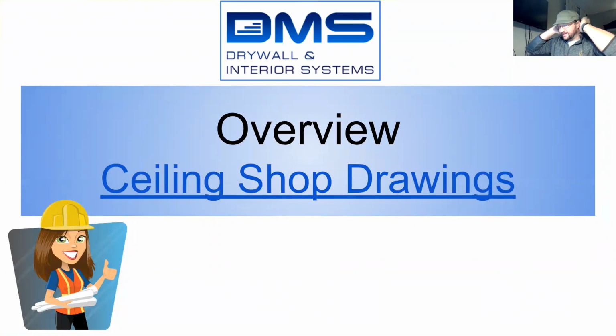Okay, welcome everybody. Today we're going to be doing an overview of how to do ceiling shop drawings. Now there's two types of shop drawings. There's the engineered shop drawing, which is usually meant for the exterior metal stud system of the exterior part of a building, where an engineer has to calculate how much load and what size stud is needed. That's a whole other company that we hire in order to do that because they have to stamp the set of drawings. So that's the engineering side.